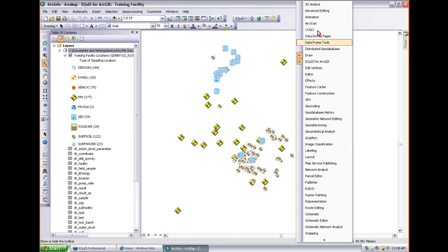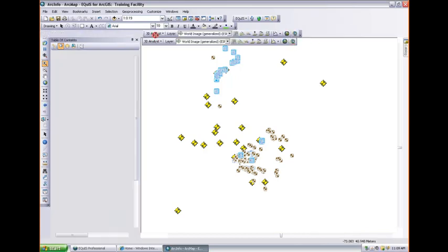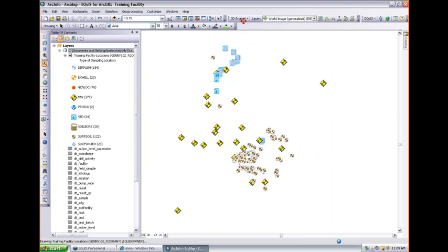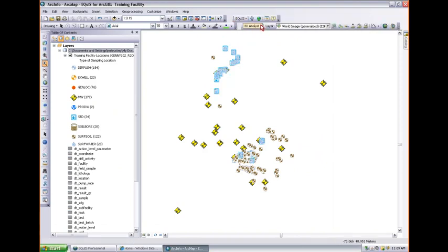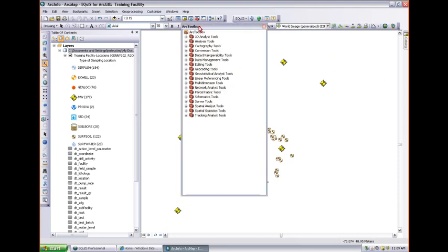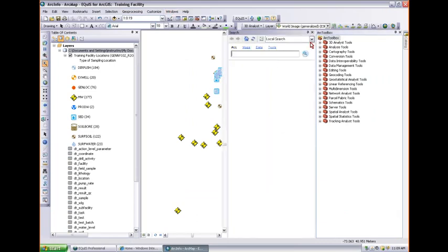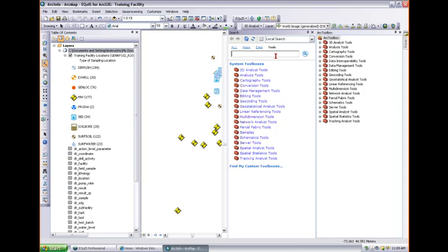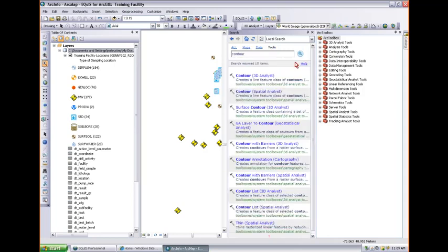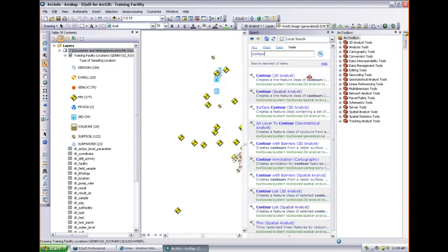So ESRI has Spatial Analyst and 3D Analyst for doing this. They essentially share the same rendering engines. They have 3, I believe, to create the grids. I guess they're now in geoprocessing models. So we click this ArcToolbox, and we can dock it now in Arc 10. We can use search across this also. Window search. Same search where we searched online, but now we want to search for tools. And we want to do contour. So here's all our contour, Spatial Analyst, 3D Analyst.